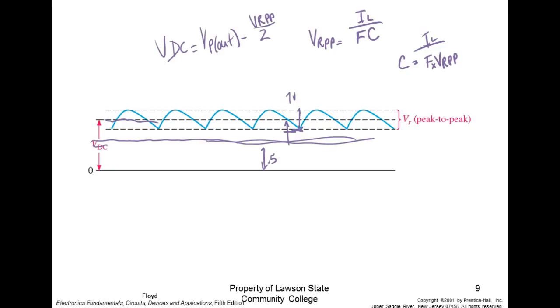And now you got it. That's about all there is to designing one of these things. So if you wanted a 5-volt supply, you'd probably buy maybe a 6.3 volt transformer. That would give you almost 9 volts out, and then you would regulate it down to 5 volts. And now you could have a pretty good deal of ripple up there.